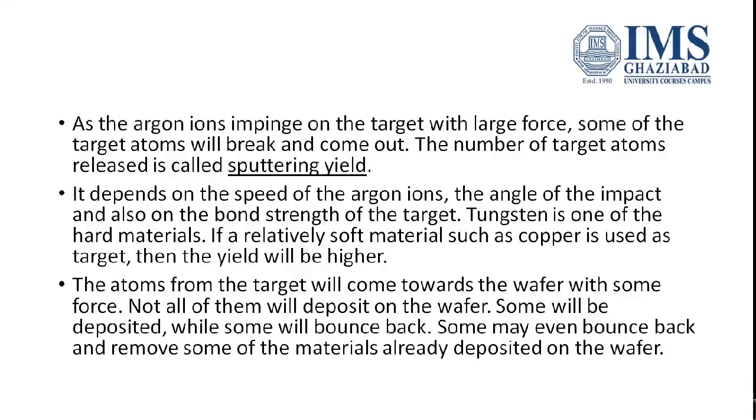Similarly here, the argon ions impinge on the target, which is the material you need to deposit, and that target material will finally deposit onto the silicon wafer.